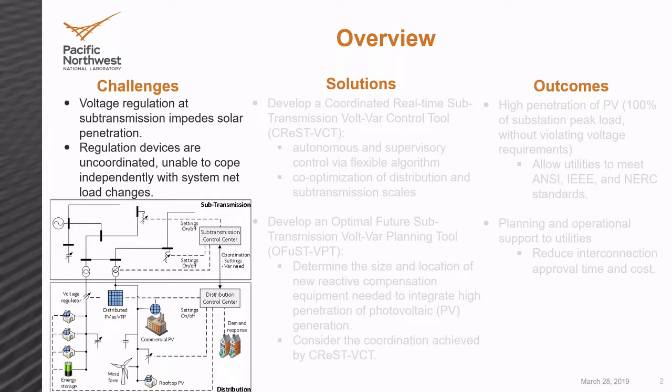Typically, the power system is designed for one way of power flow direction, from power plants through transmission to loads. But in the last maybe decade, this story has been changing, and we are having more of what we call active distribution network, more distributed generation, which creates the potential of power flowing both directions, flowing back from distribution to the transmission network. A lot of work has been done on the impact of distributed generation on the distribution network, but very little work has been done on the aggregated impact of distributed generation on the transmission network.